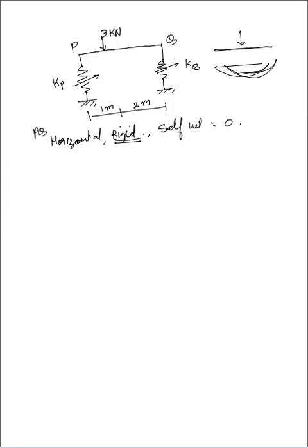P. We have seen the figure. The beam is resting on vertical linear springs at the ends P and Q. For the spring at the end P, the spring constant, that means stiffness, is Kp. Stiffness is basically action upon displacement.